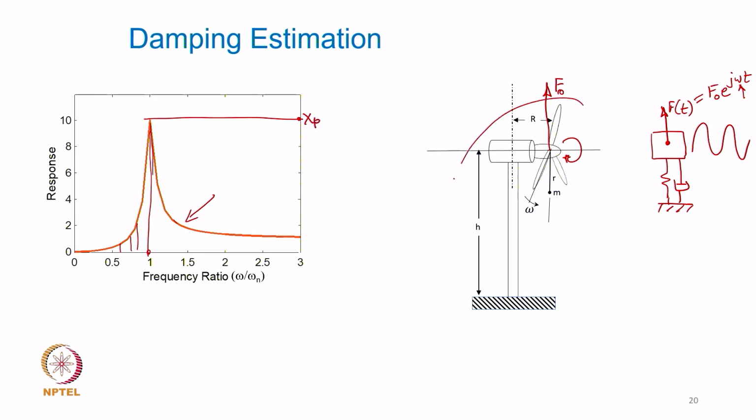Now, most of our mechanical vibratory systems, as you see here, are not going to have a dashpot hanging around here and there, right. They will have structural inherent material damping. Okay. So, damping in most mechanical systems is going to be less than 0.1. Okay. So, they will have a much lower level of damping, and so it is almost every time that we say that this omega p is very close to omega n, which means that the peak is observed close to the undamped natural frequency of the system.